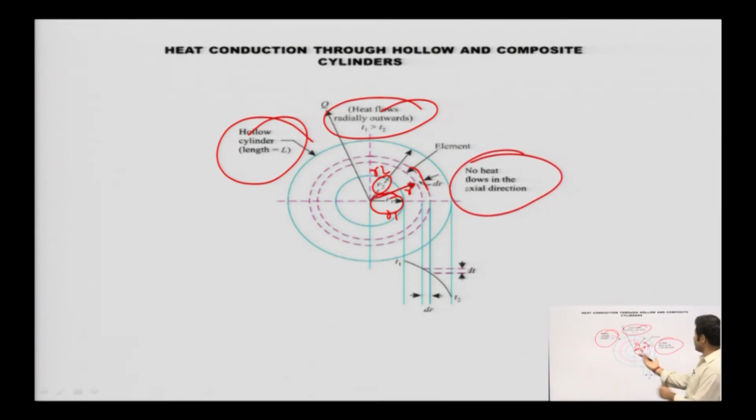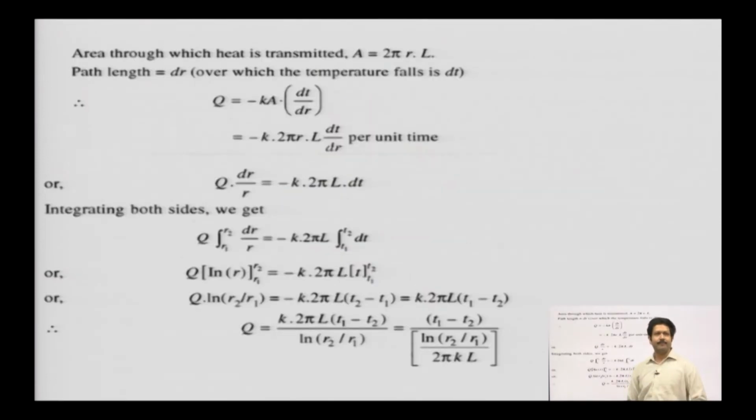Okay, so this is all about the diagram. Let's talk about how to derive this. You need to note down the thermal resistance of conduction through a hollow cylinder. Till now what you have learnt is the thermal resistance when heat is getting transferred through a slab, that's L by Ka, but now it's something else.